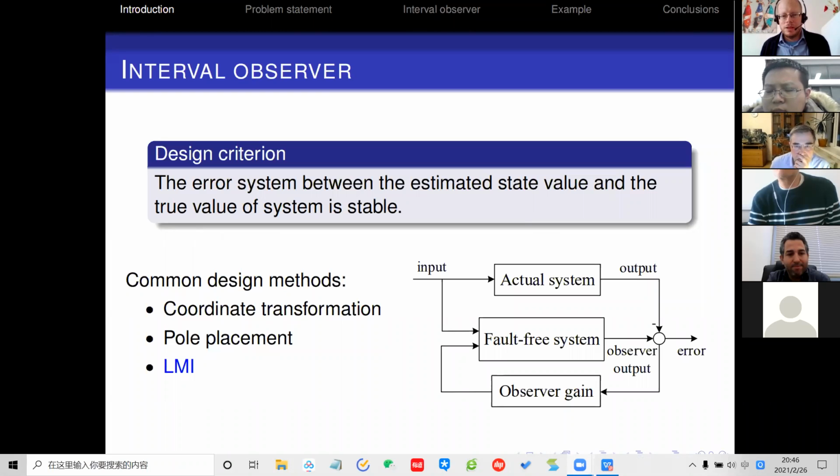That's something you could enforce a little bit by eigenvalue constraints. This would be something like pole region assignment instead of pole assignment: not placing hard values, but saying we have some subdomain of the unit circle in which you want your resulting eigenvalues to lie. This would more or less represent physically reasonable variation rates of the states. That's just some opportunity for fine-tuning the procedure.